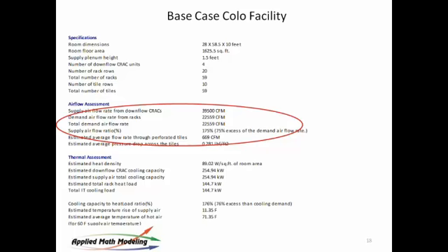And again, let's now take a look at the flow rates of the supply versus return, and you see right away that they're out of balance. So this is the pre-simulation report that comes from CoolSim. Before simulation, I have simply taken the 39.5, which is what we just determined was appropriate for supply, which is a conservative number, considering that it was blowing harder than that according to the factory specs, and we compare it to the demand of 22.5. So we've got far more airflow than we need to satisfy this room.